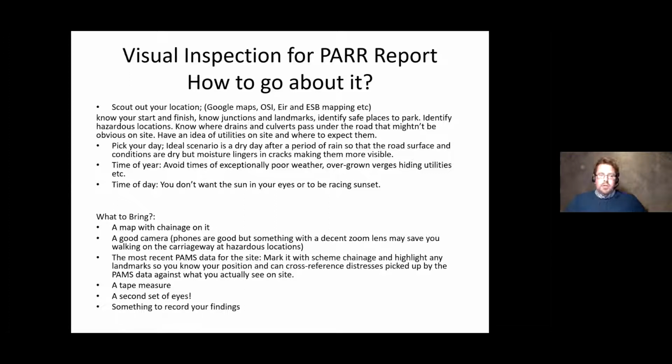Scout out your location, go check Google Maps, the OSI, and likewise check your utilities mapping, Eir, ESB. They'll give you an idea of where their utilities are relative to your scheme, both overground and underground. Also knowing from your maps, you can safely determine where your start and finish locations are. You can identify safe places to work, safe places to park, and know any hazardous locations where you need to stay off the road.